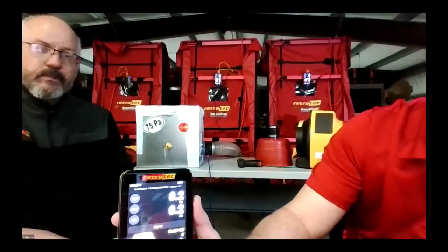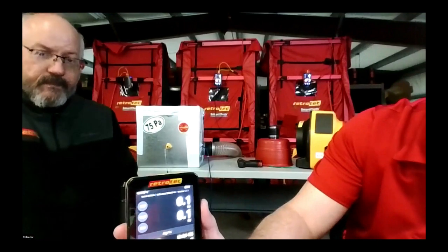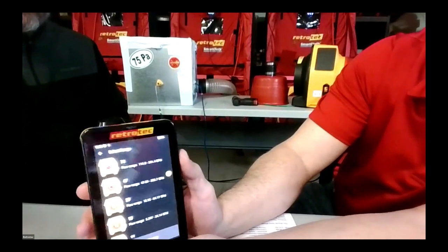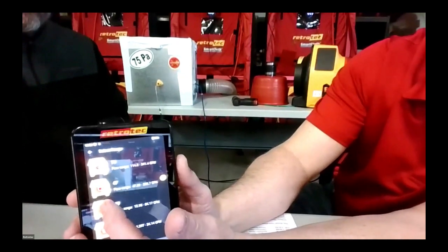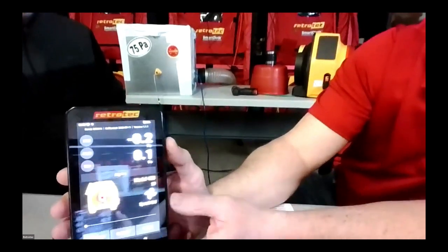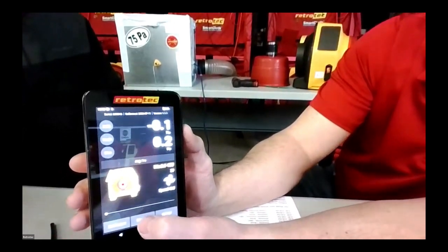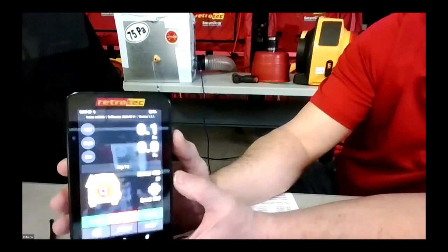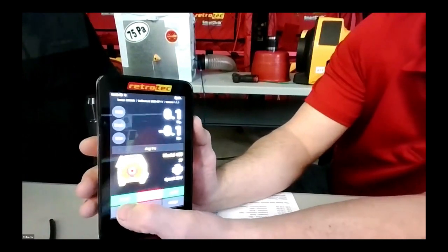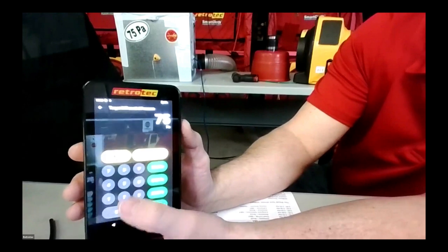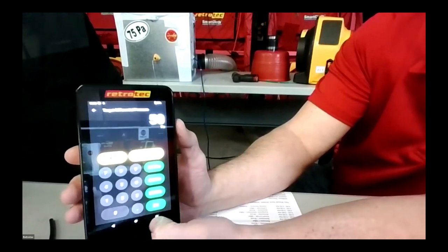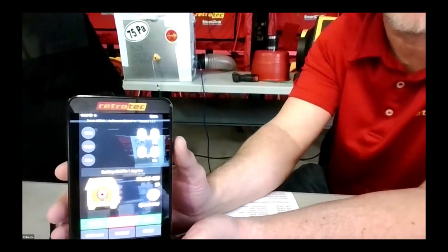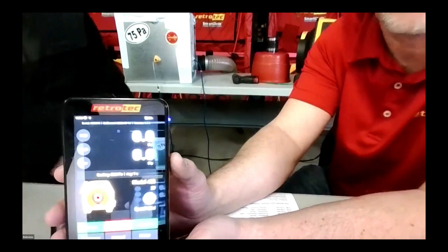If you need to change your configuration, you touch the icon of the fan. Oh, where's it at? And you can select your new range configuration. It also tells you what the range is on that. You set your speed. That's the fan speed, so you can go 25%, and that's going to take the fan to 25% and just hold it there. As opposed to set pressure, where you would be seeking a target pressure. And it's going to seek that, and so as things change, it will constantly seek the 50 pascals or whatever you have it selected to.